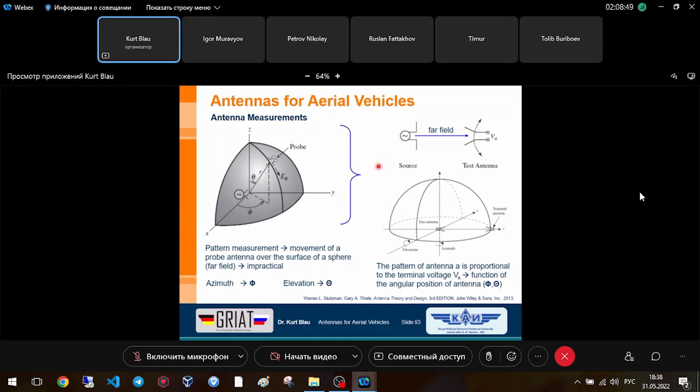The only thing we have to consider is if we have antennas with a larger reflector, high gain antennas, then to achieve the Fraunhofer region or the far field, we have to bridge large distances. If you are outside of a building, on a measurement test area outside in nature, it's not a problem. But then you have a dependence on the weather.